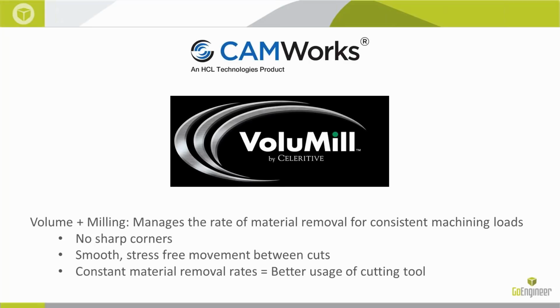It is fully integrated inside of the CAMWorks programming scheme, and it's made up of 2 words: volume plus milling. It manages the rate of material removal for consistent machining loads. The great thing is that the toolpaths it generates have no sharp corners. Everything is very smooth and stress-free, and it'll extend tool life. It'll engage the material to the full flute of the tool length, and you're going to get better usage and control of that cutting tool.